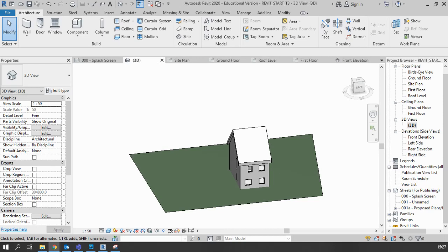Guys, so what we're going to do now is add a bit more detail into our plan for our house. So we're going to add the external walls into the model as a traditional brick and block wall. Again, in Revit, the template has pre-built or preset wall types. Here, we're going to create one from scratch, which is somewhat more advanced if you think about it. But yeah, we'll give it a go.